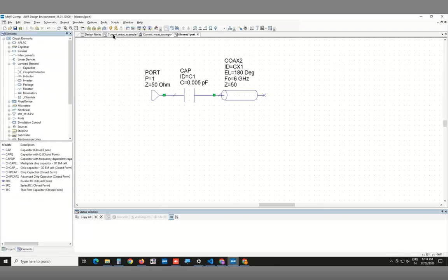You can compare this to a Fabry-Perot resonator, like an optical resonator. You have one mirror here, and then you have a partially transmitting mirror on the other side, right? So waves can go back and forth, but here they will leak out as well. And energy is also coming in from this side. That's what this type of resonator is, right? We had mostly in the early part of the class looked at LC resonators, but this we also discussed towards the end. We had shown some examples of that. But anyway, it gives you exactly what to draw. So this is what one had to draw.